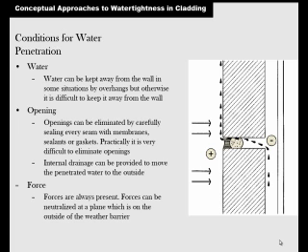It can be sealed with sealants and gaskets, but there is a force, and the force is always present. It can be neutralized at a plane on the outside of the weather barrier. Here they're showing you that the water will drip down, and if there's an opening here, it'll find its way in, because this is positive pressure and negative pressure, and the water will be drawn in if it can get in there in any way.